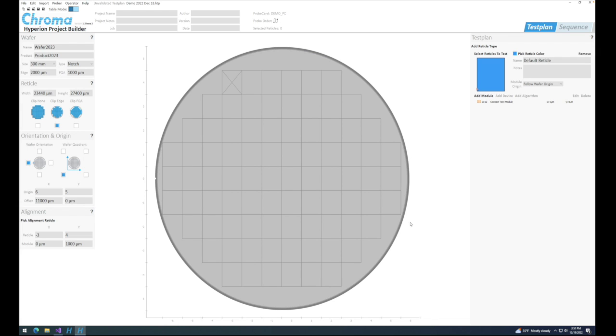Alignment file names for each orientation must be provided. Switching between the two does require that the wafer be unloaded, reloaded, and realigned, as well as additional bond pad scrubs being suffered. So doing all vertical and then all horizontal modules or vice versa is strongly recommended.